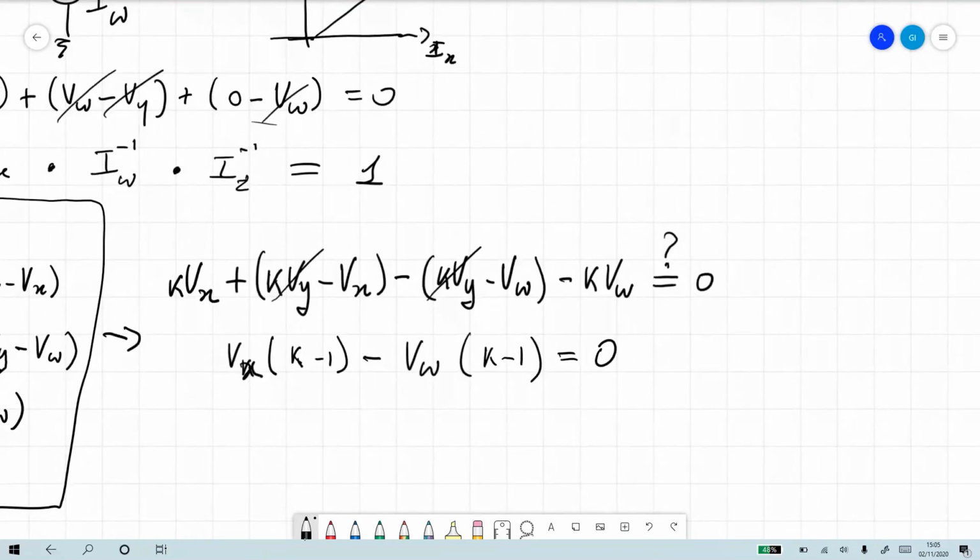Yeah, so it's this translinear principle in subthreshold. It's useful to get an intuition of what's going on, but it does not allow you to have a precise output of what's going on. You always have to keep in mind that there's this kappa that gets in the way.